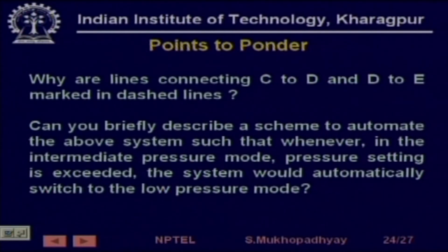One thing I wanted to mention is that in many cases you will find that I have said that some limit switch operates and that operates some solenoid. So how does that happen? You have to have a scheme for that. Sometimes you can have a purely electrical scheme, sometimes a simple relay type scheme, or sometimes a PLC based scheme. So various special arrangements are needed.